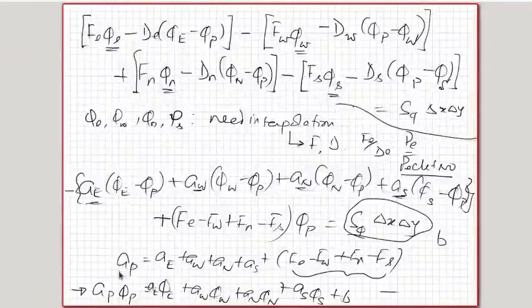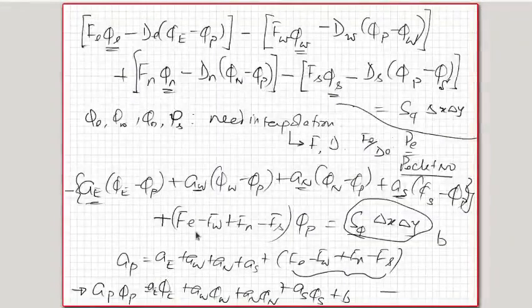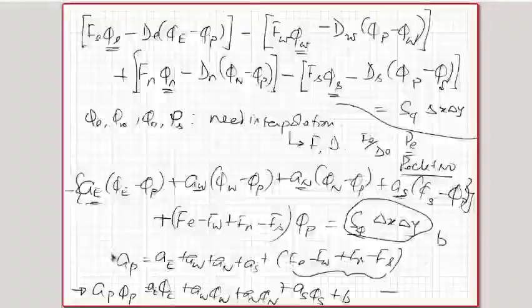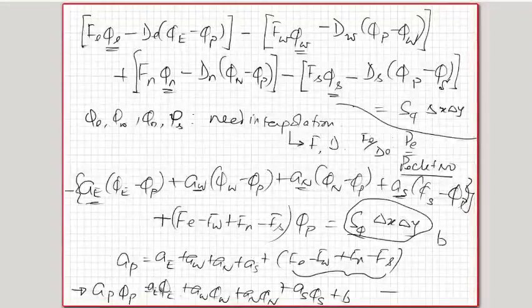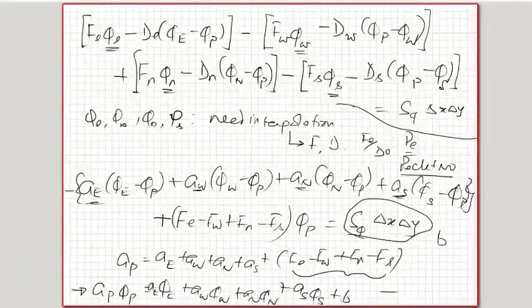That can be the case, for example, for the energy equation once the velocities are all solved for, and the vorticity equation once the velocities are all solved for. But it is not the case for the momentum equations because they have mutual dependence, because AP, AE, AW would also be functions of unknowns, and there is also non-linearity, so there is need for iteration.